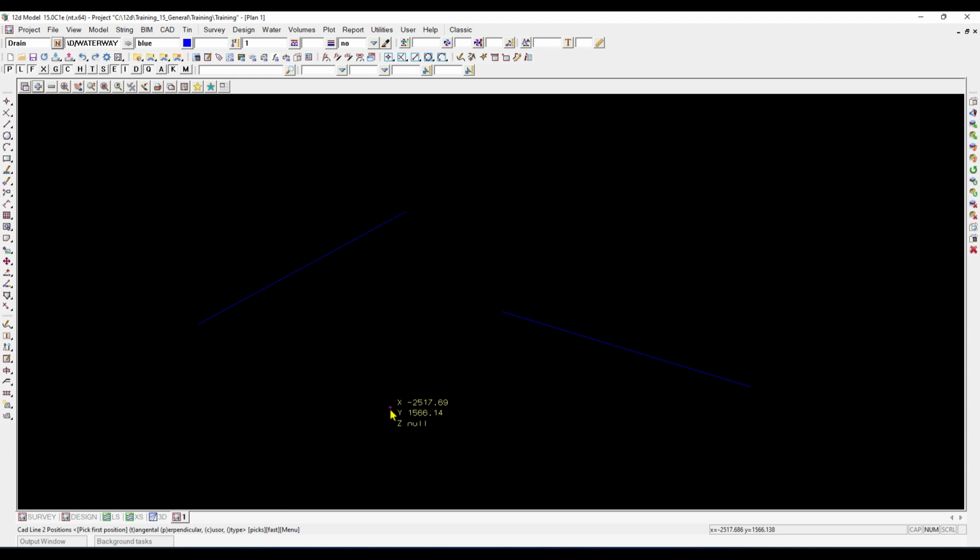We have our CAD snaps. They sit just below your CAD properties toolbar, and you'll see these 5 boxes with little blue boxes or lines around them, and those are your CAD snaps. If you hover over them, you'll see there's a snaps CAD point and a snaps CAD intersection, and again they've got a black triangle, so they've got a flyout, and if you click and hold, a lot of options pop up. What we're going to do as part of this exercise is show you how to bring those toolbars up so you don't need a flyout.